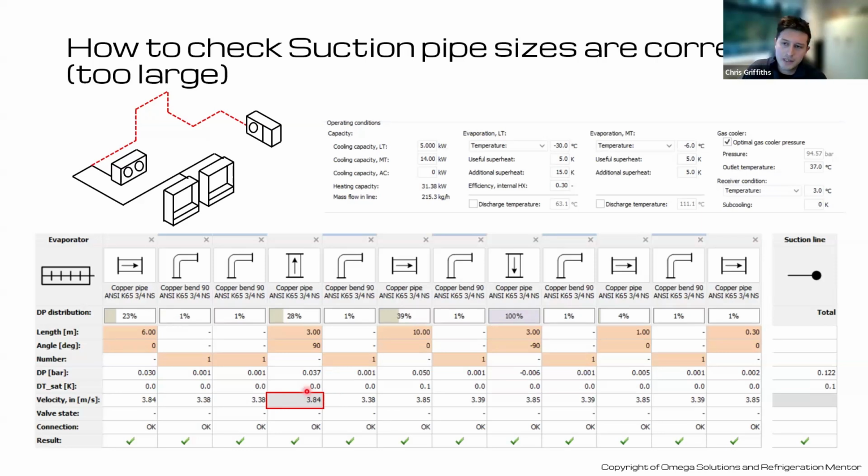So the rule of thumb previously that people have worked with is you drop your riser size on the vertical either 1 to 2 sizes below your horizontal. CO2 is a bit more forgiving than HFC in terms of carrying oil back to the compressor. We don't often find we need to step it down. I've designed a lot of stores out there where, yeah, you've not needed to whatsoever.